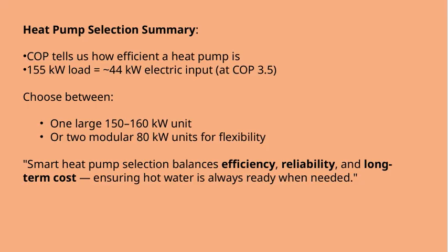For example, if we have a 155 kW load, that typically requires about 44 kW of electric input when the COP is around 3.5. So, the system's efficiency really impacts our energy consumption and operating costs.